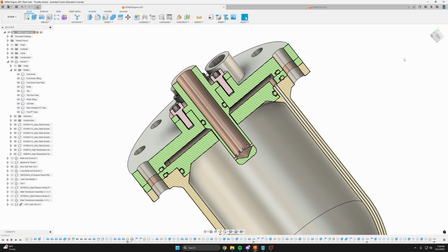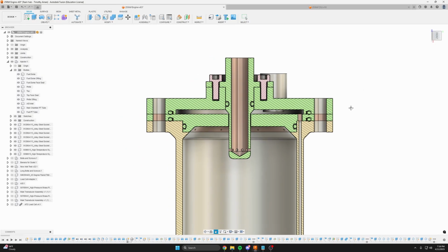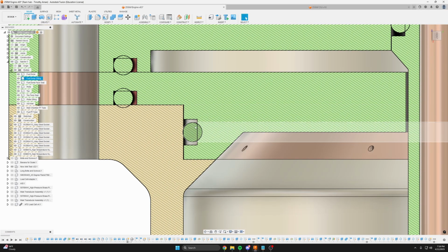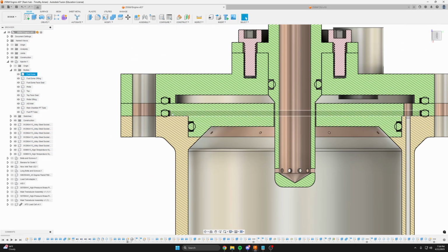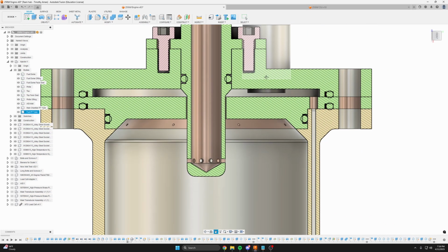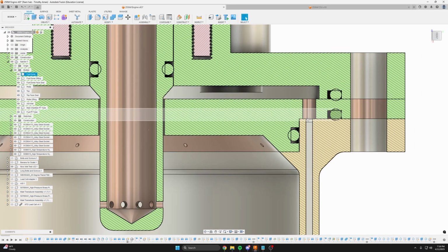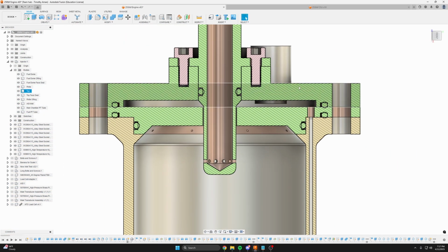There are a lot of resources out there that will tell you exactly how to design these O-ring grooves for gases, for liquids. I personally use the Parker O-ring handbook, which I will also link. Half Cat Rocketry has their own design guide that's a little looser on the tolerances than the Parker O-ring handbook. But I found that if you machine it to the specifications of the Parker O-ring handbook and you use a liberal amount of grease, and you of course deburr these edges and such, you can get away with some pretty tight tolerances.